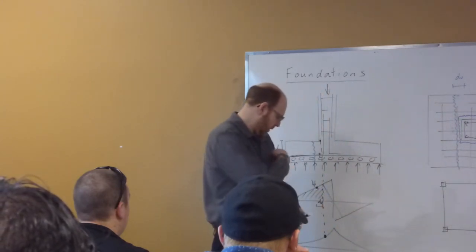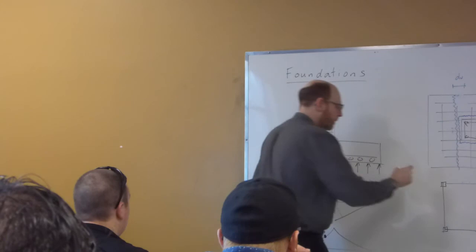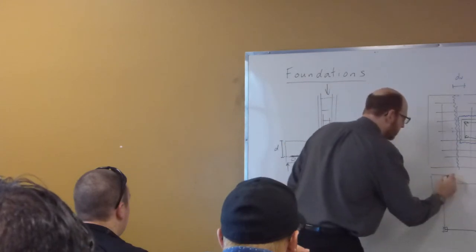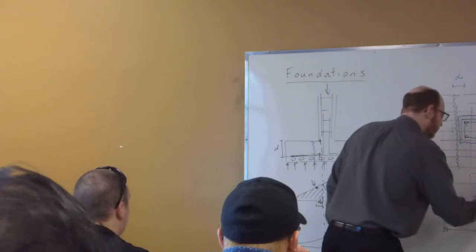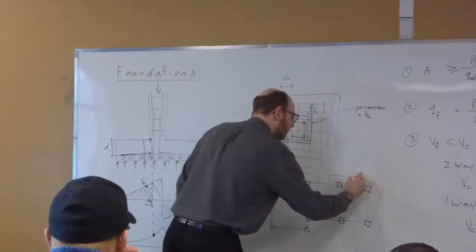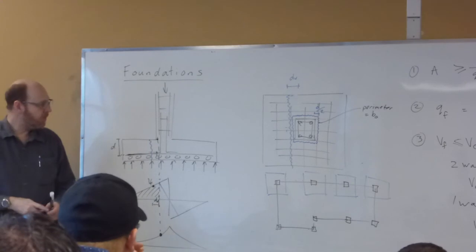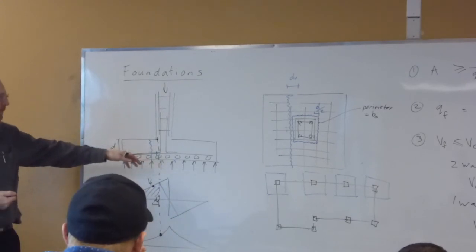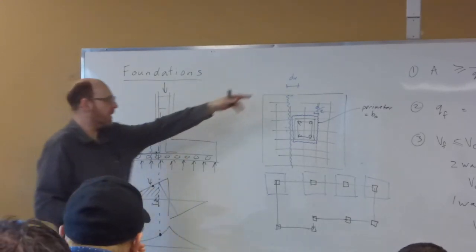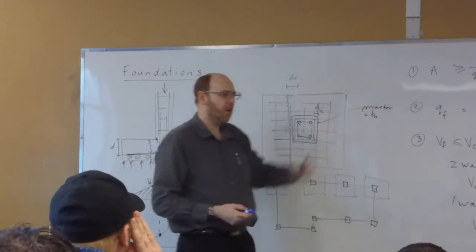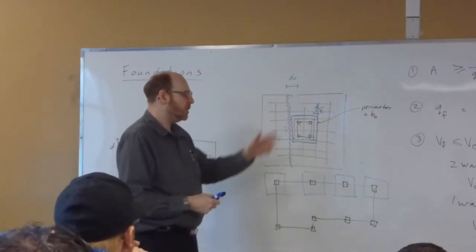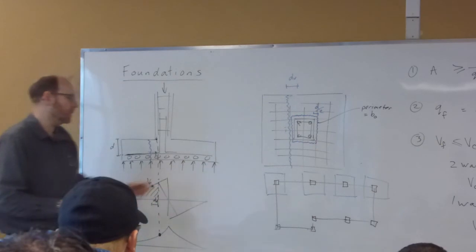And underneath those, we're going to put our footings. For the most part, we've got a footing that sticks out like this, and it's not too bad. So you get the idea there. Now, we've talked about the design of this footing, how we start with calculating our area based on the allowable soil bearing pressure, checking our shear, doing our moment calculation, and so on.